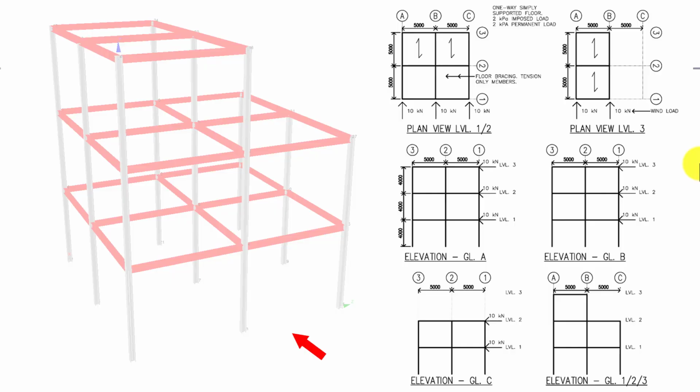The first thing we need to do for our structure is to sketch a bracing layout. Now, how are the loads, all the lateral loads, going to get to the foundation? And just remember, our braced bays are going to carry the lateral loads, our columns carry the vertical loads. Now, we have the wind blowing from bottom right to top left, so blowing across the structure.